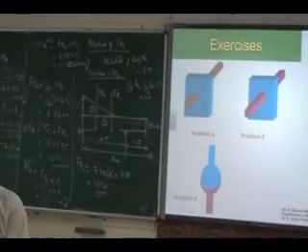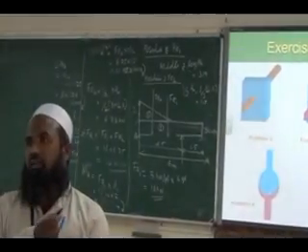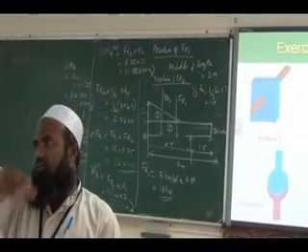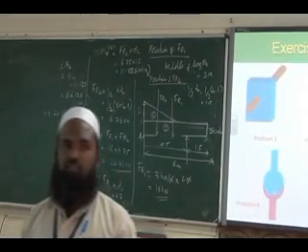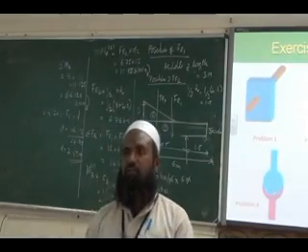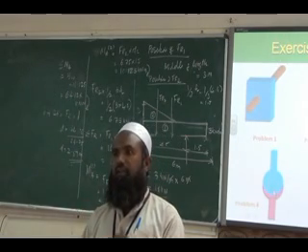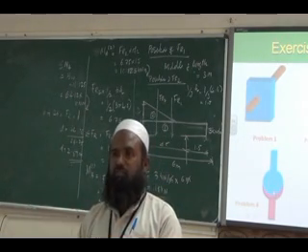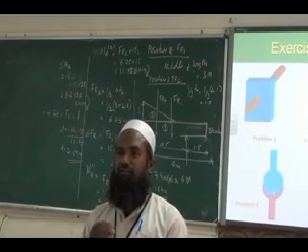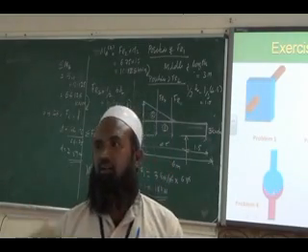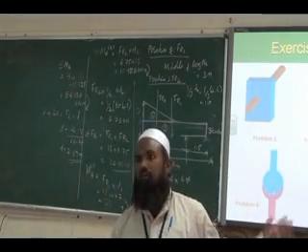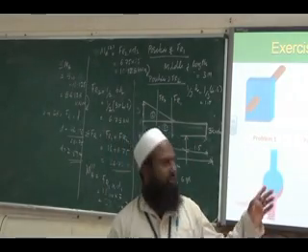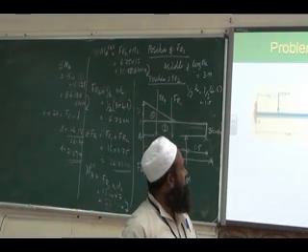A ball and socket joint. It can rotate in all the directions. Rotation around X, Y and Z is possible. No translation is possible. Okay. So according to the degrees of freedom, the way it can move, you will have reactive forces. If it has the freedom to move in one particular direction, no reactive force will exist in that direction. Okay. So this is about the reactive forces by drawing the free body diagram.